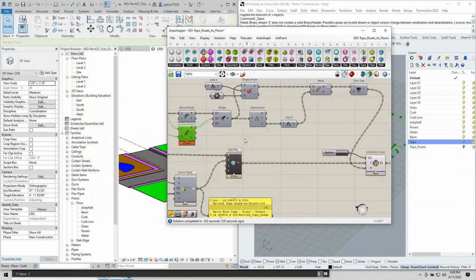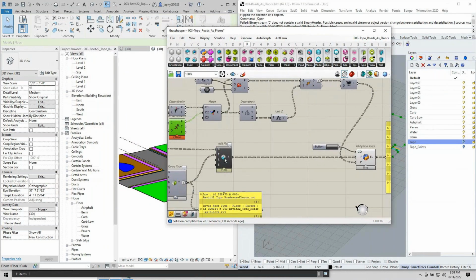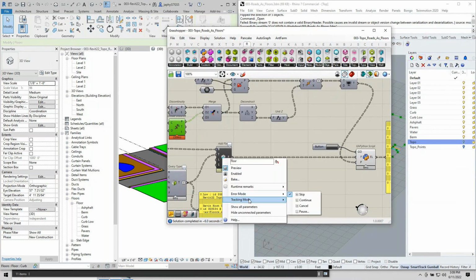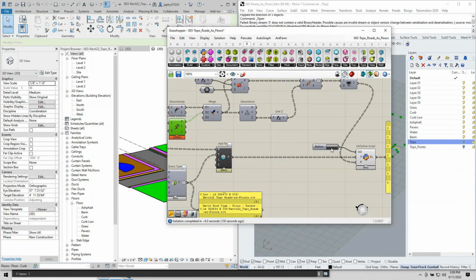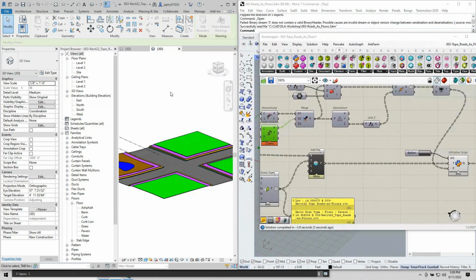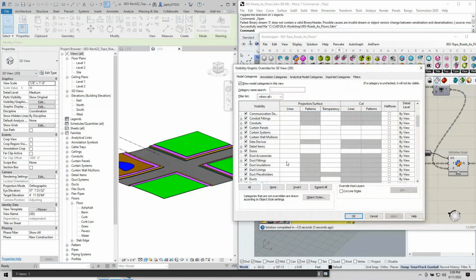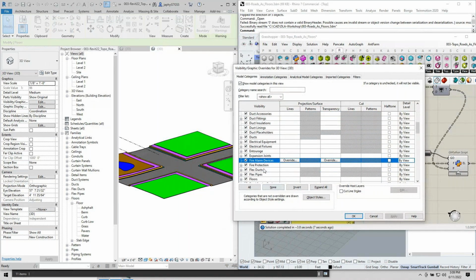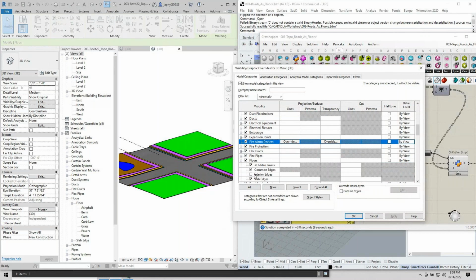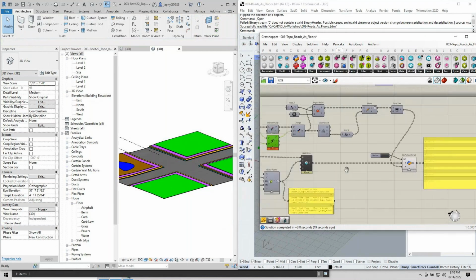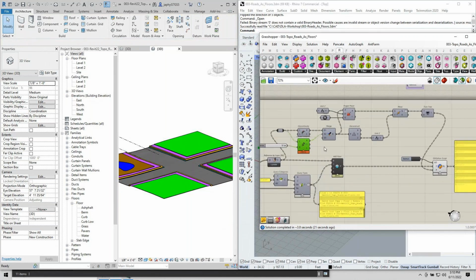Now we can add this in as a different resolution, and I'll put it back onto update, recreate, and you'll see our floors are going to be less faceted. So it's a good way to control the resolution of those objects.